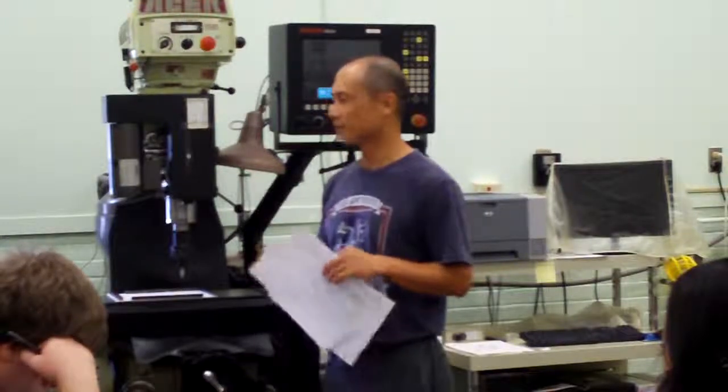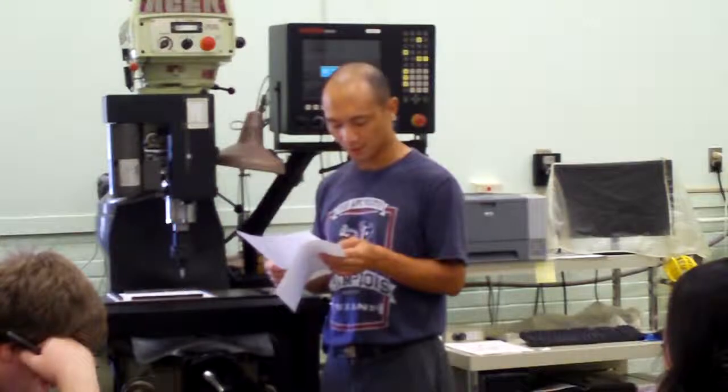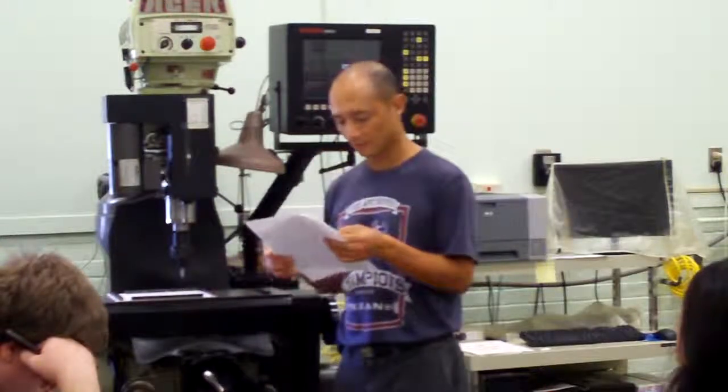So the operator may get confused that supposedly he was trying to bring the tool to the workpiece, but nothing happened. He may think that the machine is bad or something's wrong, but actually nothing is wrong. It's just that the mode is wrong. The mode should get back to absolute mode, then everything is fine. So that's why in the next line, they directly get back to G90. This just gives you an idea in which situation the incremental mode is more convenient.